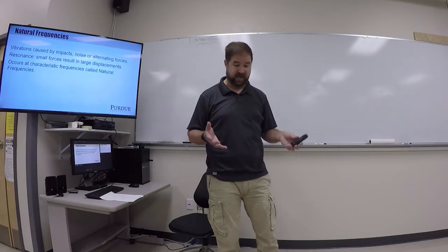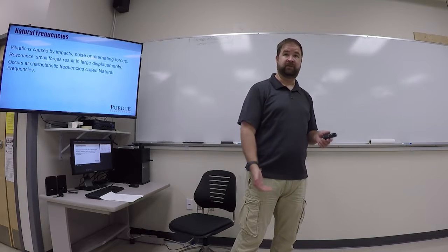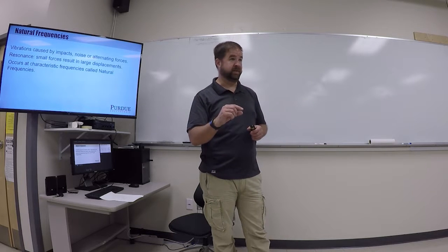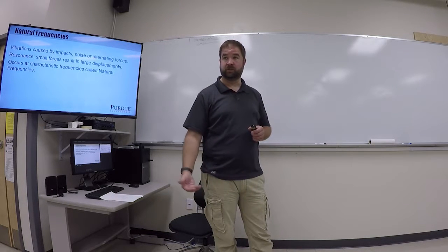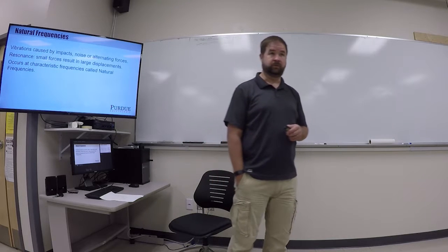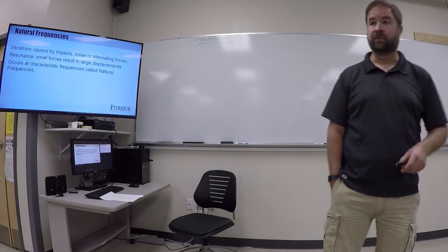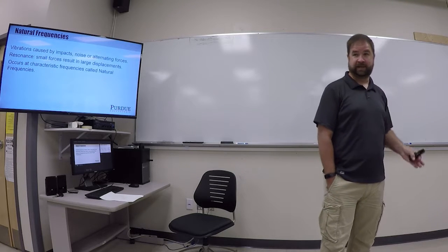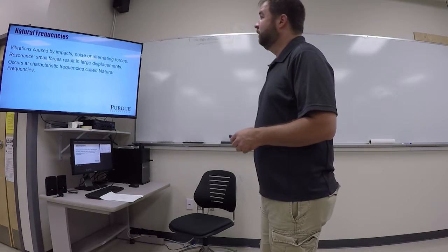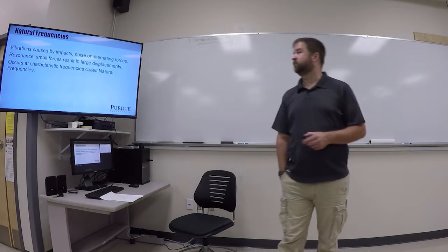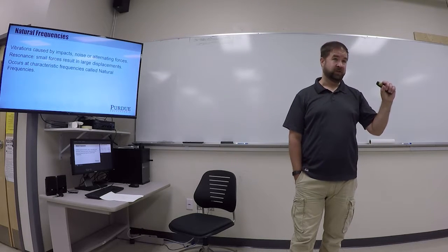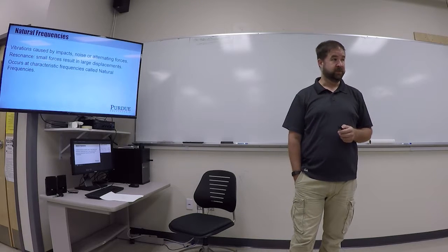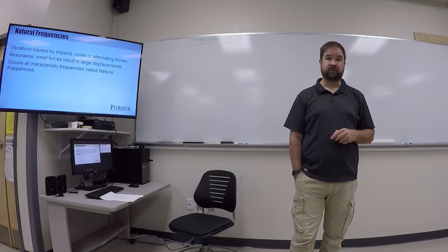Okay, so it can be a real problem, and if it's not treated, then obviously it makes the structure unusable. People can't stand on a floor that's shaken up and down by a half an inch. Or even if the magnitude is significantly less than that, the vibrations are detrimental to productive work. Or if your monitor won't stay on your desk because it keeps vibrating off the back, that's a problem. So, small input forces result in really large displacements. That's the characteristic of a natural frequency problem.